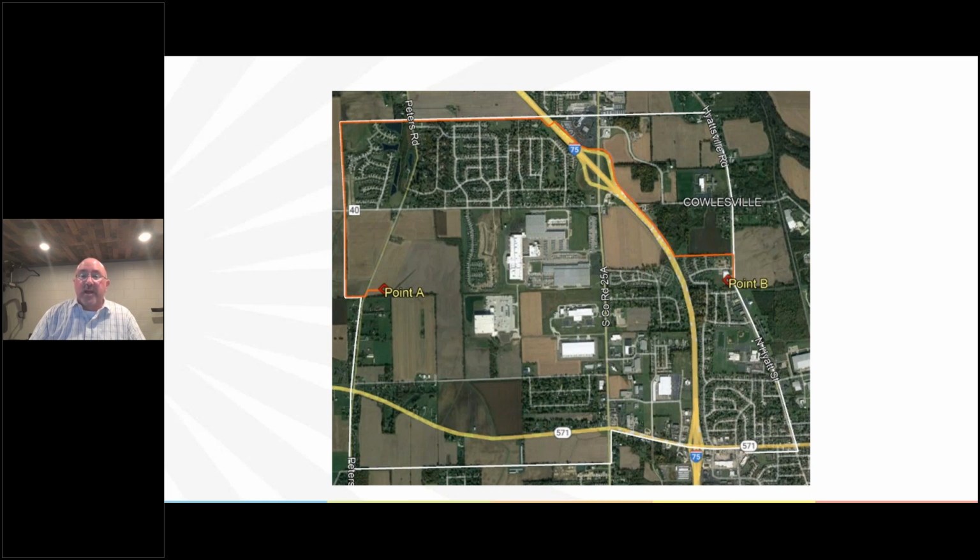We also ran into FAA issues with proposed pole heights impacting the flight surface of an airport to the north. So the same area where you see that 75, if you go to the northwest and extend further west and then extend south, we put poles into the notice criteria tool, and it started coming up with poles that needed to be 70 feet high. So we were looking at more like poles that were 110 feet high.